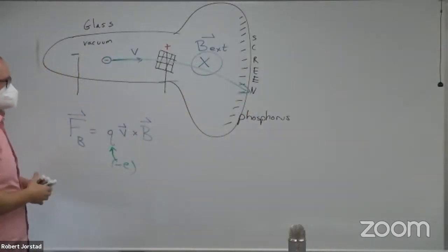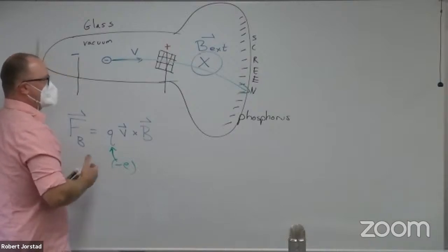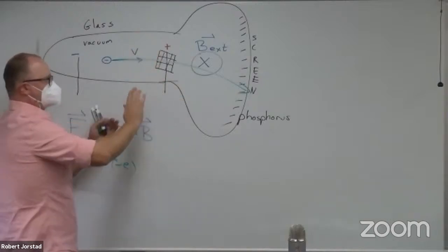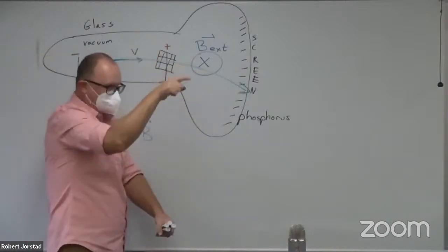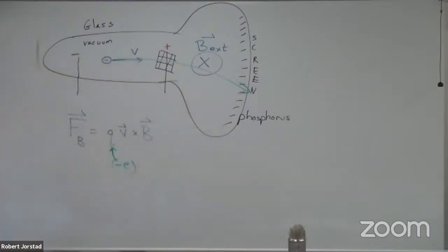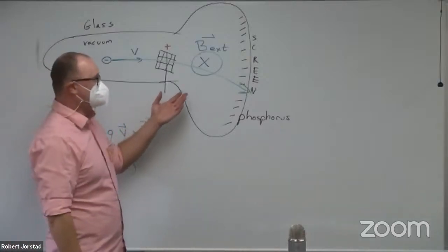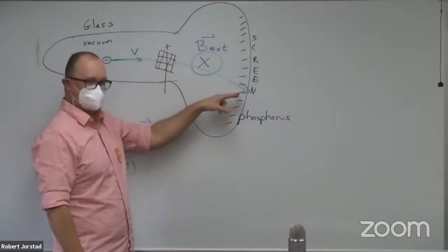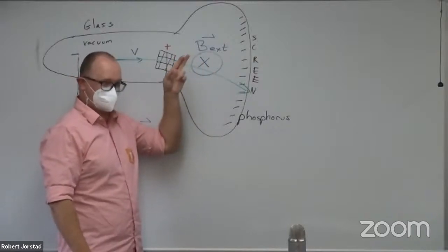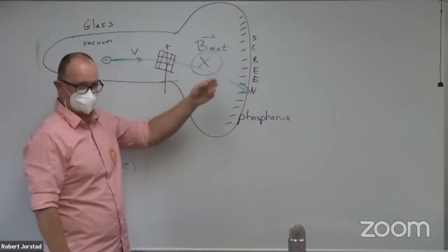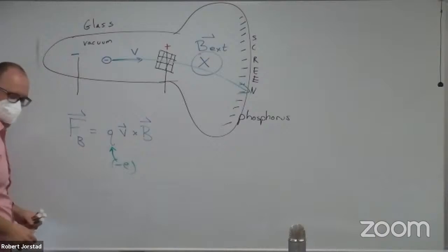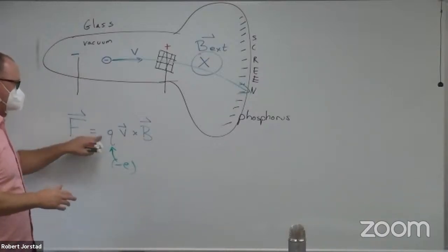And the idea is how an old cathode ray tube works: you could have a variable B field or a variable electric field, basically, and have this thing go up and down. You could have another one to have it go left, right, and you just trace it out, and that's how they make these little patterns. It's amazing they work at all. And then to get colors, you need to have red, green, and blue pixels be energized. So you need to be able to aim the beam precisely enough to hit the different colored pixels. It's crazy when you think about it. Mind-blowing. All right, anyways.